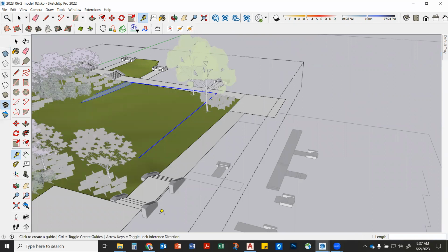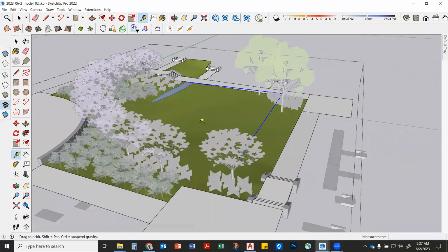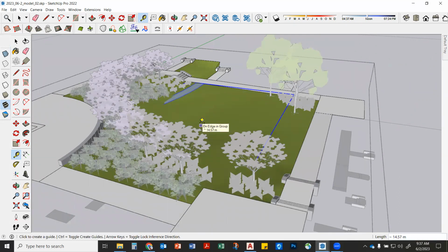That's the total drop that walk needs to make, right? Now we could actually calculate the slope, but when I first designed it top to bottom, it should be right at 5%. If we took the total length of that walk, divided 1.42 by that total length, it would give us gradient, right?